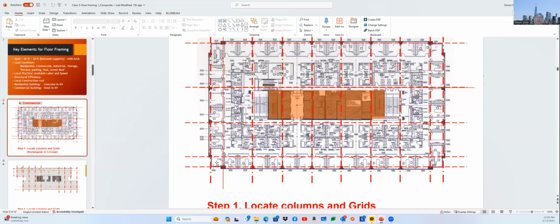So I think there are requirements for maximum egress safety evacuation distance, right? At the farthest corner office, you should be able to evacuate and access the stairs within some distance. So if a building has a footprint, obviously the architect should figure out the maximum distance requirements and place the stairs at the right location to meet this egress safety evacuation requirement.